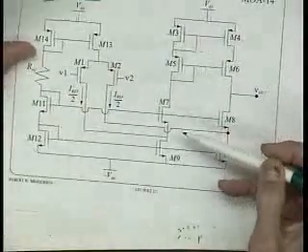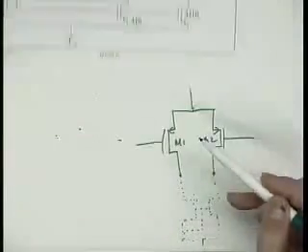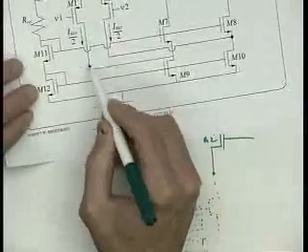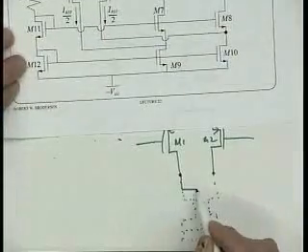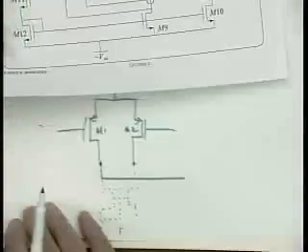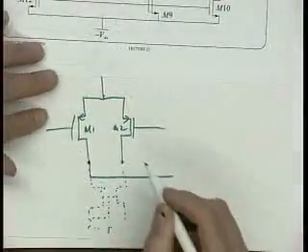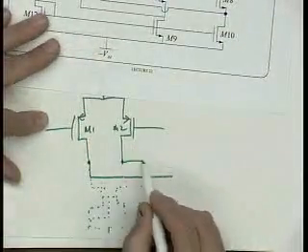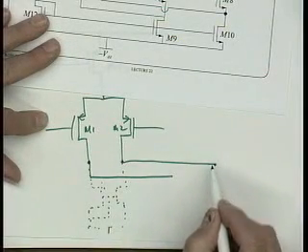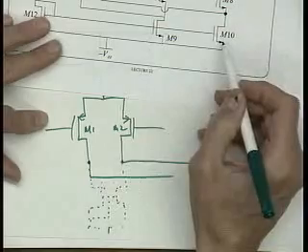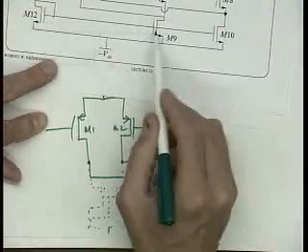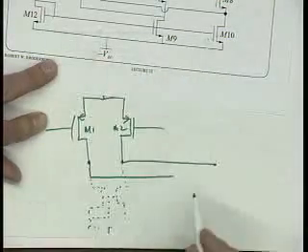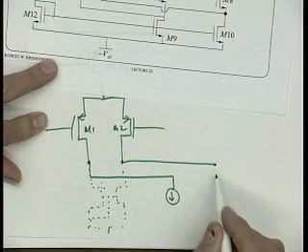Okay? All right. The way to look at this thing is this. We're taking this lead here, it's this wire right there, right? I'm bringing it over here. Unfortunately, okay. Here is this lead, that's this one here. We're bringing it over here. And then what M9 and M10 are, if you look at this, here's a diode connected transistor, and here's M9 and M10. Those are just two current sources. This is just a simple current source. So M9 and M10 are just, so let me just put two current sources down here.